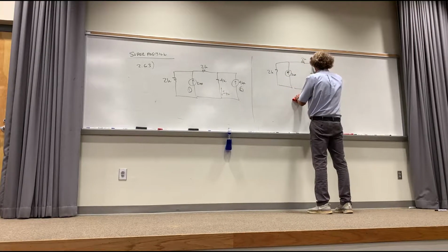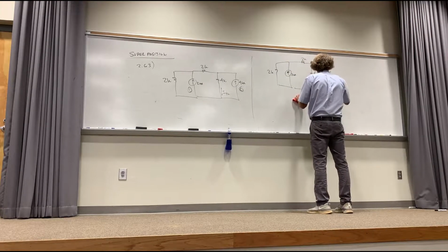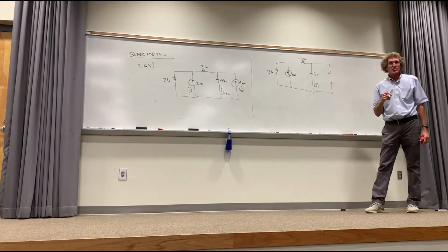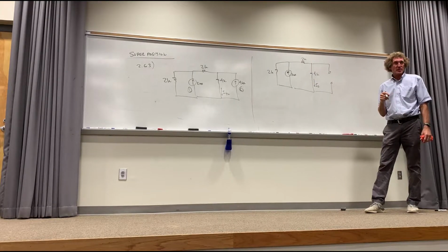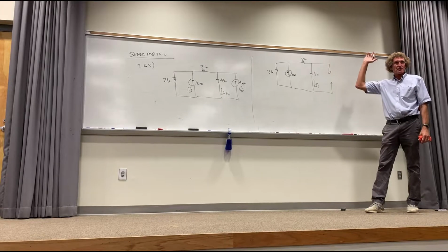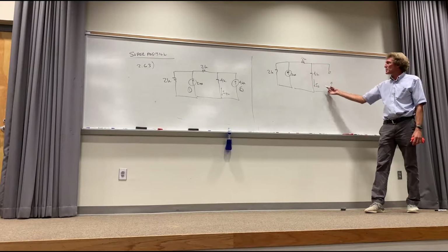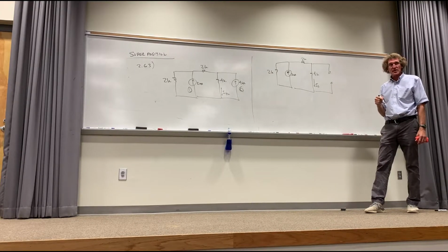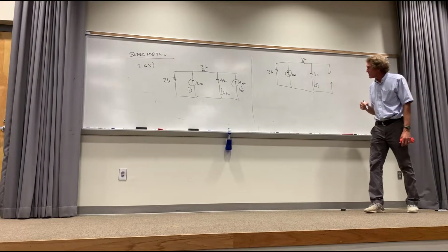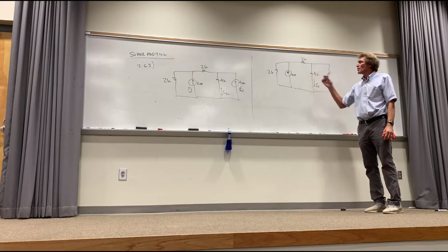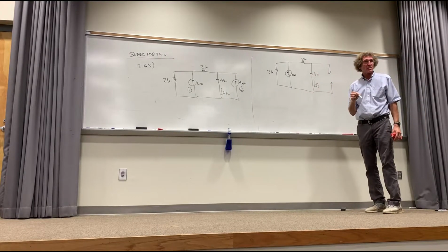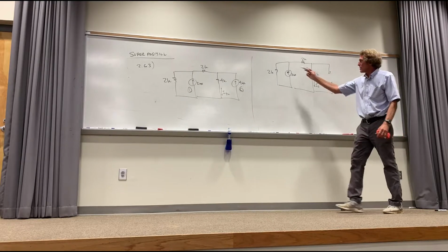And this one becomes an open circuit. You see how I turned off the second source? I literally made it an open circuit because it's a current source. How many can see this? Follow me what I'm doing? I literally cut it out, didn't I? I ripped it out. Now, I want to find this current. Now, I want you to watch this and you'll see it very easily. When I do this, can you see the 2 and the 4K are in series? Does everybody see that? They're in parallel with that 2K.